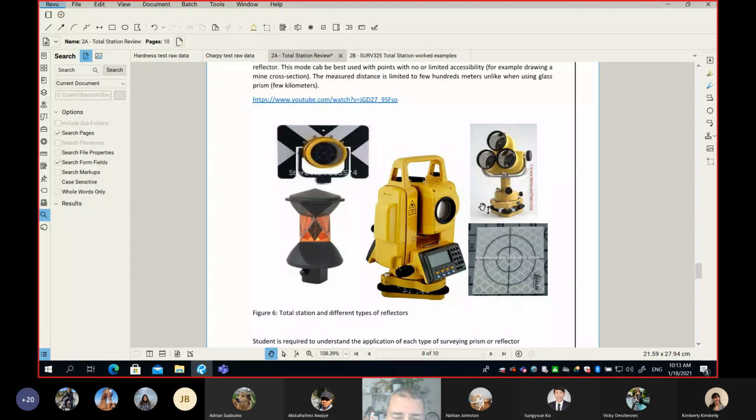When they are vertically above each other, it means the easting and northing are the same. Remember this: when the rod is vertical, the center of the prism is above the point of interest, and they have the same easting and northing. In 99% of applications, we use this one. I want to take you a little bit further, to the picture on the top right.